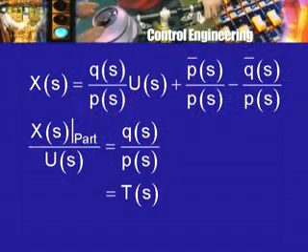Now, this polynomial P(s) occurs in all three places, and if you remember, when doing the inverse Laplace transformation, we had to do the factorization of P(s), and therefore the roots of P(s) are simply the poles of the transfer function T(s). The roots of P(s) determine the nature of the transient response, or the terms that depend on initial values of x, initial values of u, and this part also may give rise to terms that involve the poles of P(s).